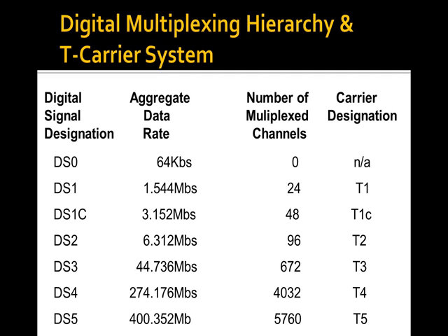So we've actually addressed that part of the problem simply by going to digital transmission. We code audio. Coded audio isn't immune from attenuation, but it makes it easier to detect at the end. You're not detecting subtle variations in the analog signal. You're trying to tell whether a particular pulse is a 1 or a 0. Well, if I set those pulses sufficiently far apart, 0 volts and 10 volts, pretty easy to tell, even if it's 6 or 7 volts and gotten a little ragged around the edges, it's still pretty easy to tell I've got a pulse there. So I've made that part of the job easier.